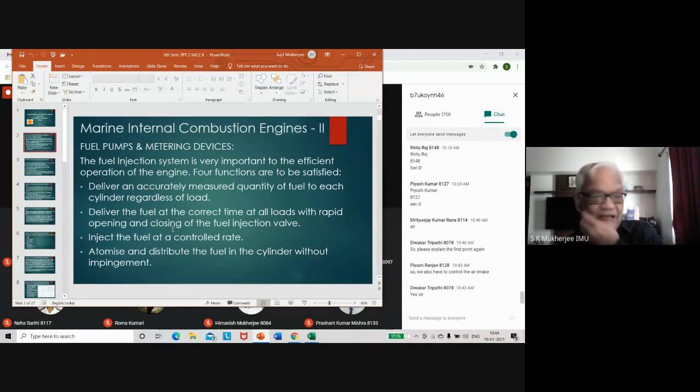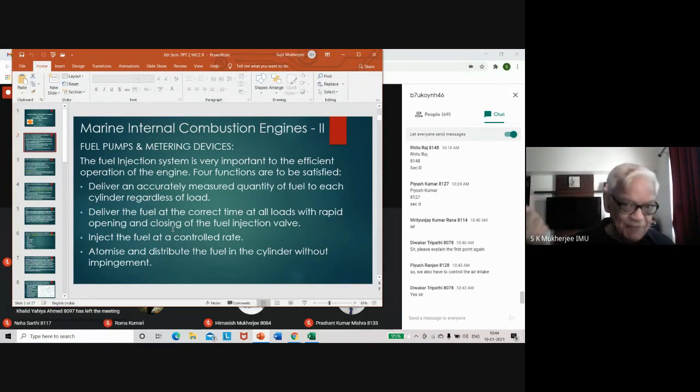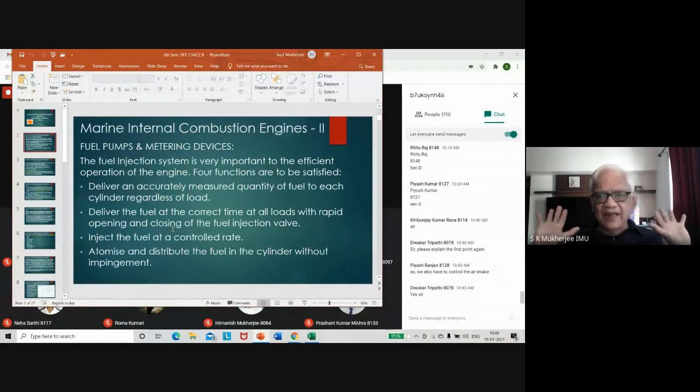All right. The air pressure is determined by, number one, the electric blowers. These electric blowers are used when the engine is running at part load condition. That means the turbocharger is not capable of delivering air to the engine. So that is the time you put the automatic switch on for the electric blower, and the air quantity coming in will be regulated.